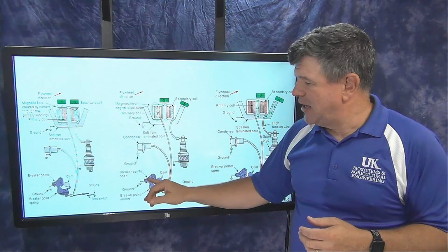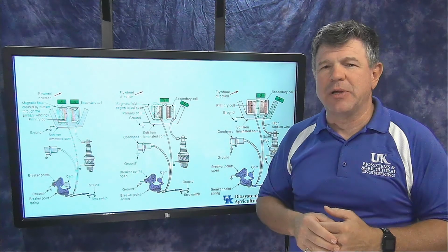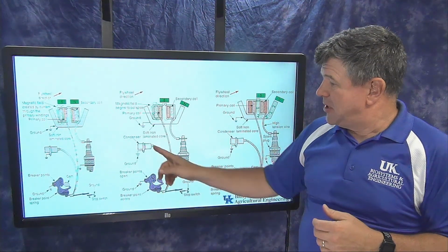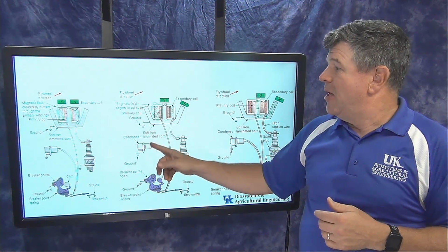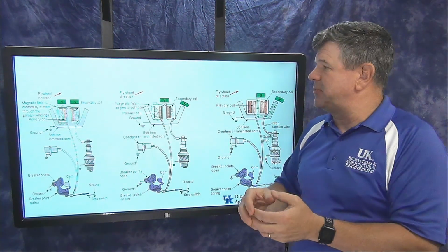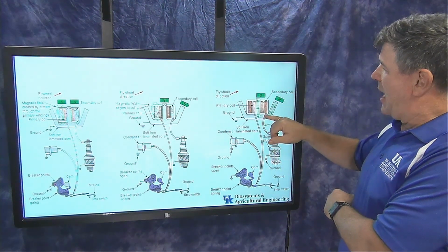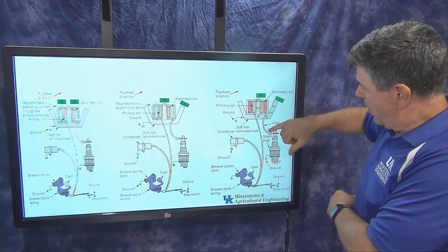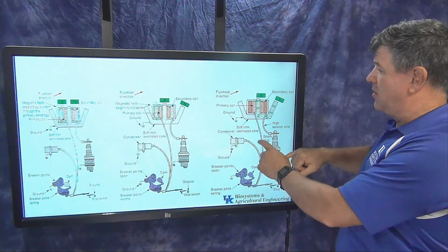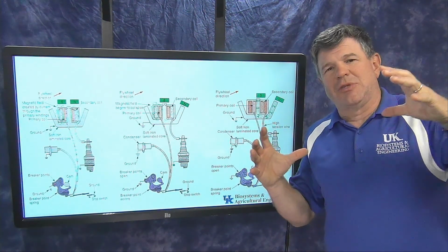That also could be an indication of the wrong gap in there and so forth, that these are open and closing too much or not closing completely or something like that. So, at any rate, going back to what's happening here, I opened this switch, some of that energy went into that condenser there, that stopped the current flow up here, I get the inductive kick, the magnetic fields are collapsing, boom, now I get a big voltage, and so if I come over here, I've got energy now coming out of that secondary coil, going down into my spark plug, but look, I'm actually also recovering some energy from the condenser, so the energy that was stored up in there, remember we said it's kind of like, almost think of it as like a balloon.